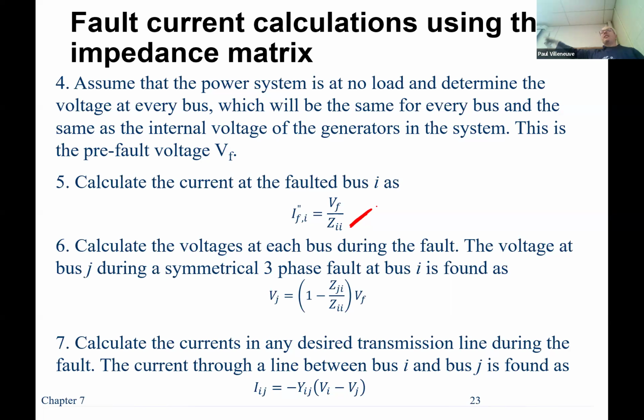And you could say, and I know those guys in the back are going to start to harass me about something like, well, Paul, you're lying to us because line protection is used with distance relays. But the distance calculation is based on the amount of current that flows. So when the current is lower, your impedance is going to be higher, which means it's in a zone 2, which is a delayed element. Now they're like, maybe I shouldn't argue with them. Zone 2. What's that? Wyatt's ready to jump.